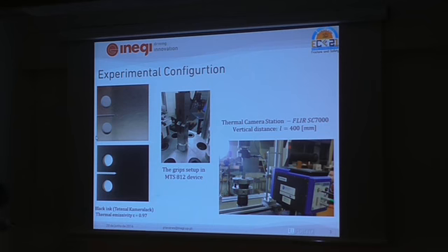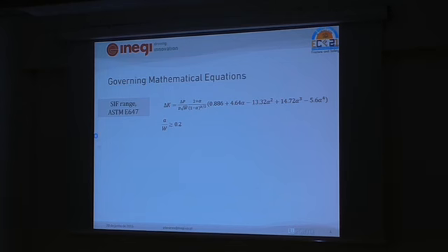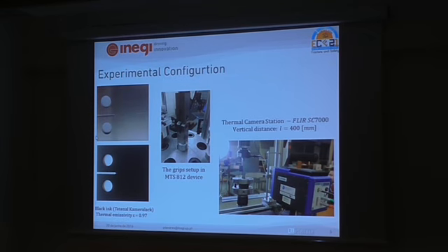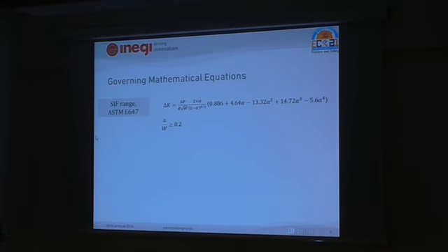We are using a FLIR SC7500 camera, and the rest is pretty much standard. We're using very high emissivity camera black ink that gives us nearly 0.97 for thermoelasticity. And the rest is history, as you know.